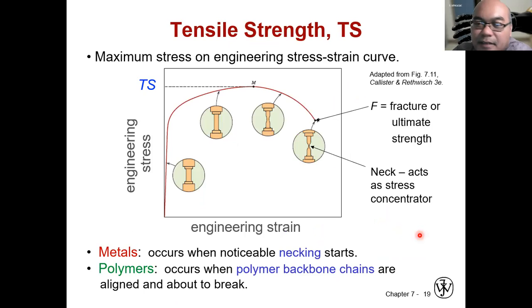Another mechanical parameter is tensile strength. Okay, still using the same sigma over epsilon graph. So this is the elastic region. Then after this elastic region, when you pull further the specimen, especially for metal, it will start to yield. This is the region where it has plastic deformation. You pull further, it will deform, which if you unload the stress, it cannot go back to its original state, because plastic deformation already occurs.